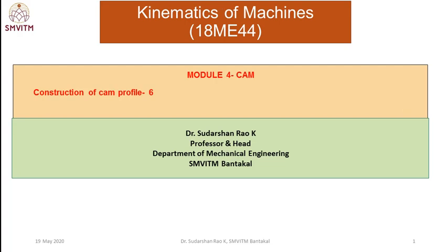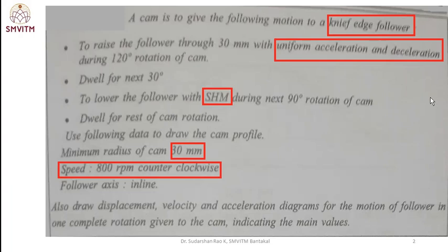Dear friends, in this session I'm going to discuss the construction of the cam profile. The cam rotates in the anti-clockwise direction, with a knife edge follower, and the follower motion is uniform acceleration for the ascending and SHM for the descending. Okay, let's see the conditions.